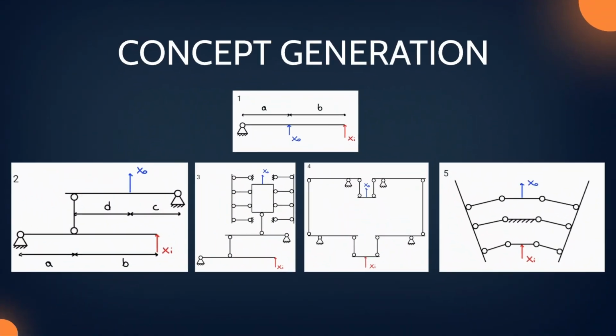Based on the QFD, a couple of concepts are formed, which can best adhere to the specifications. These are represented here. Each was considered because it best worked for some specifications. The first concept is the single lever. This was considered because it represents the easiest way to reduce the output. Even if this is the simplest solution, it lacks linearity due to it causing a rotational motion in output and not being symmetrical.